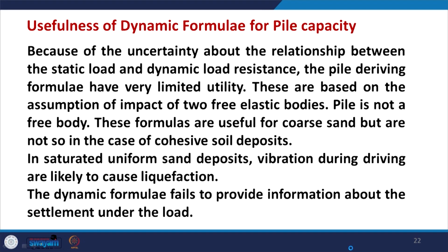Now the question arises, what is the usefulness of dynamic formulae for pile capacity? Because of the uncertainty about the relationship between the static load and the dynamic load resistance, the pile driving formulae have very limited utility, because these are based on the assumption of impact of two free elastic bodies, while pile is not a free body. That is why these dynamic pile formulae have limited applications.